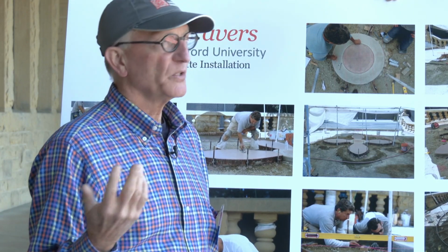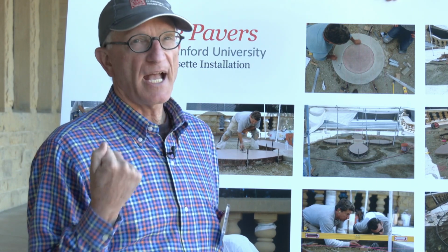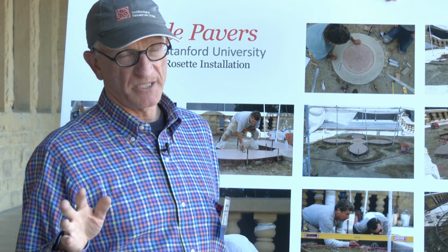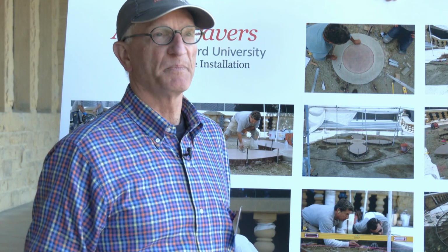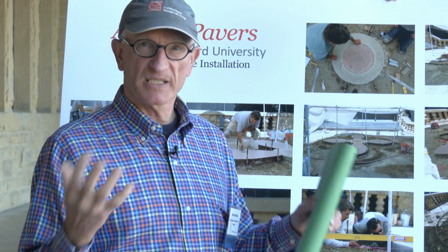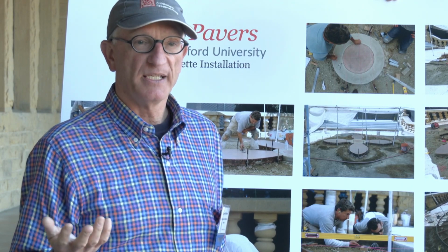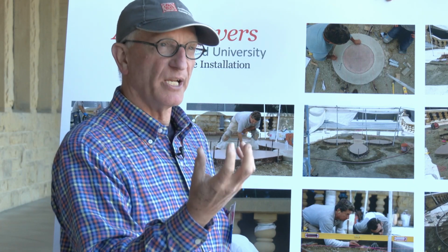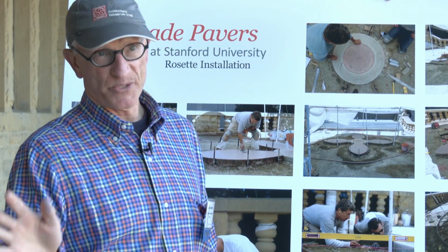I then called the university and said, we need to cut a hatch so we can get into there. They cut the hatch, and what we found was that the stain was not ferrous. It was not being caused by steel. It was actually the wood form boards that were left up into this confined space, this space that was not open in any way to the outside, and water had been seeping in through the mortar joints, and then the wood had been deteriorating and seeping out, and that's what the staining was. So we got rid of that, and we solved that part of the staining on Hoover Tower.